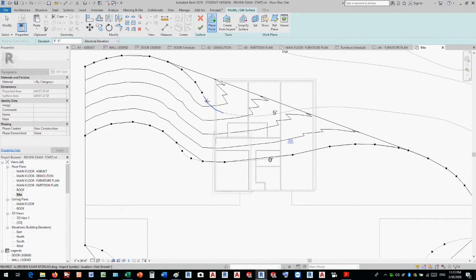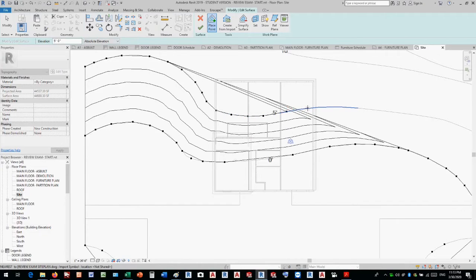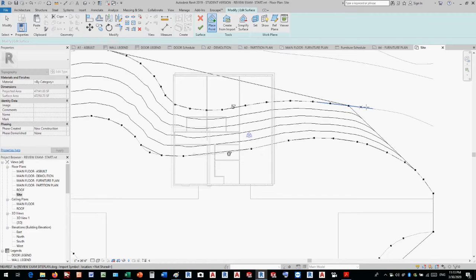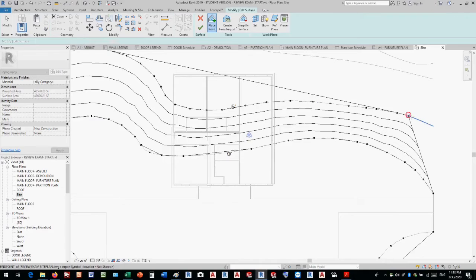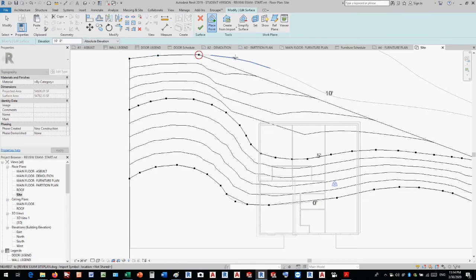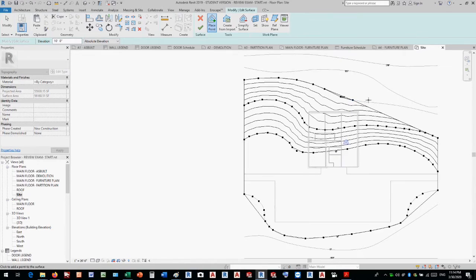Again, make sure that you have your visual style set at wireframe, because if you don't, in areas like this where your elevation is higher than 0, you may get to points where you cannot see your CAD file because your topo surface is on top of your CAD file. Okay, so go ahead. I'll keep picking points along 10 and then eventually along 15 and 20 and also negative numbers at the bottom. Okay, and I will talk to you on the next video.